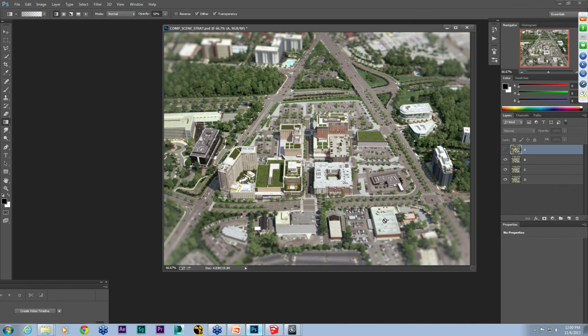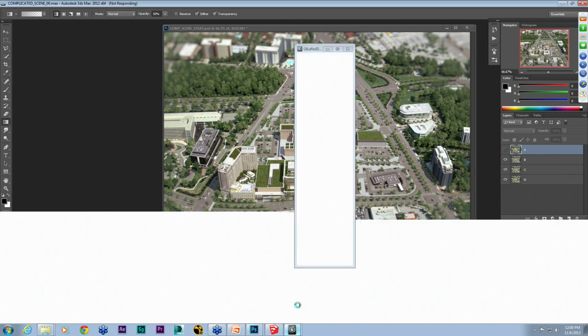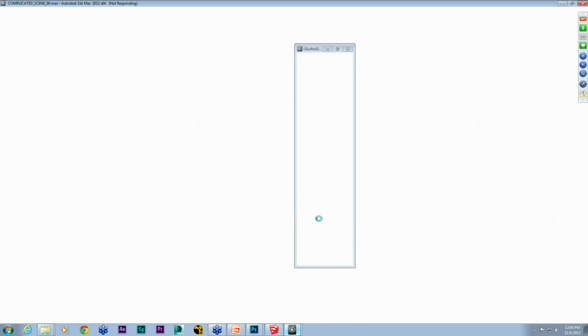So a Forest Pack or something inside an XREF tends to create more issues at network rendering time than something that's live in the scene. Again, everybody kind of has their own experiences, but that's one thing that we've learned over time, and we try to build our workflow around that.